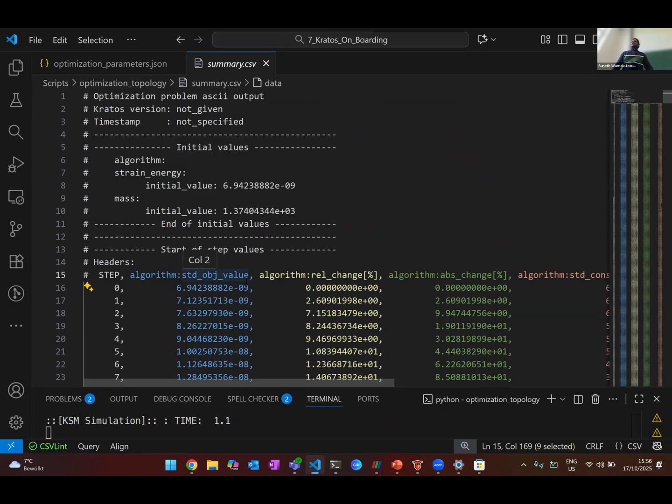That's why we use it to put everything about optimization stuff, not the single physics stuff from Kratos, because it needs the history anyway. If you run a transient optimization, you need to have a nodal history as well as optimization history on top of that. So it's nested, it's becoming complicated. That's why we have a separate container which links to the Kratos structures in optimization, which we call problem data.